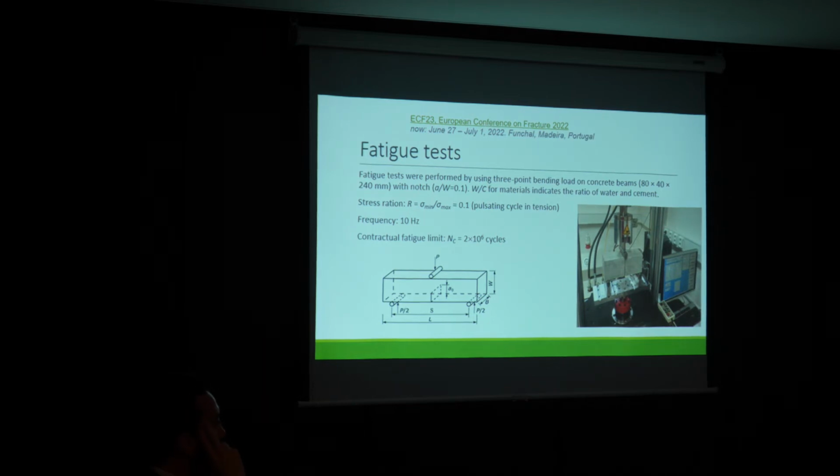They showed me that when we studied the fatigue load of concrete-like materials, up to 10 Hz it is independent, but if you use a high frequency, the material shows much better properties because there is no time for the crack to grow before the notch.